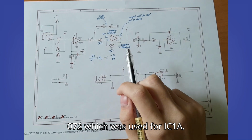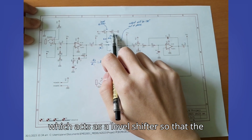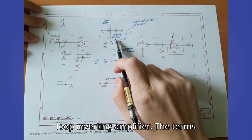For the second stage, IC1B is using the second op-amp from the same IC, TL072, which was used for IC1A. Once again, there is a voltage divider which acts as a level shifter so that the output will not be clipped. This amplifier has a negative feedback loop. More specifically, it is a closed-loop inverting amplifier.